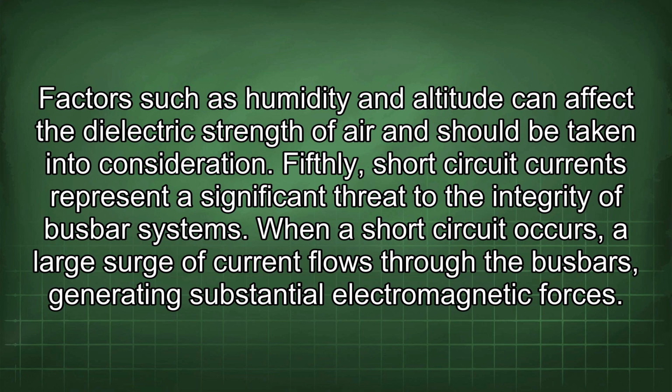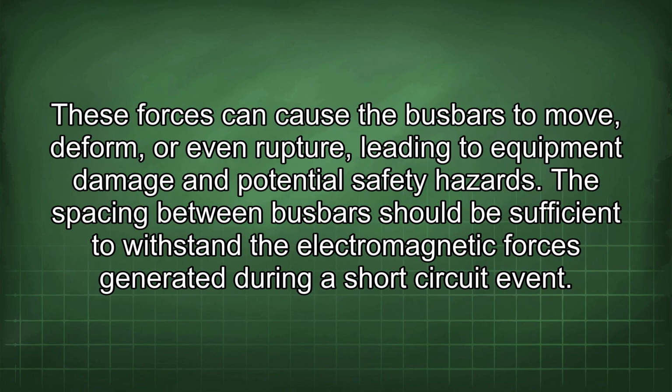Fifthly, short-circuit currents represent a significant threat to the integrity of busbar systems. When a short circuit occurs, a large surge of current flows through the busbars, generating substantial electromagnetic forces. These forces can cause the busbars to move, deform, or even rupture, leading to equipment damage and potential safety hazards. The spacing between busbars should be sufficient to withstand the electromagnetic forces generated during a short-circuit event.